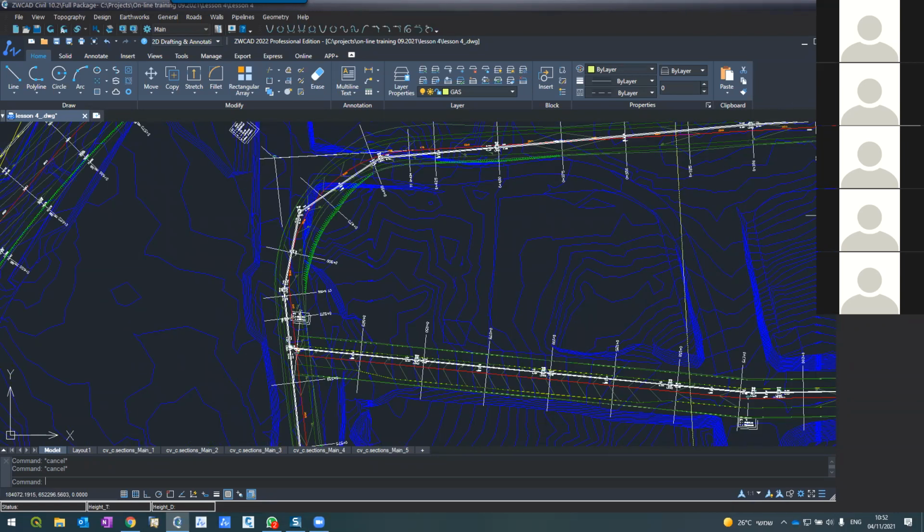So what I'm doing in the crossing, I'm pressing the filter button here. Just to remind you, we learned already about this filter button when we want to scan points, we want to scan break lines. So I'm doing the same here. Scan. Okay, it asks me, which layer do you want to scan? I can just select it from the list, or if I want, I can press select here, go to the drawing, pick the pipe and press enter, and it shows it's a gas and it's a lightweight polyline. This is what it's going to filter. So first of all, I tell the software which layer to filter and what is the type of entity which I want to filter. And then I press apply.